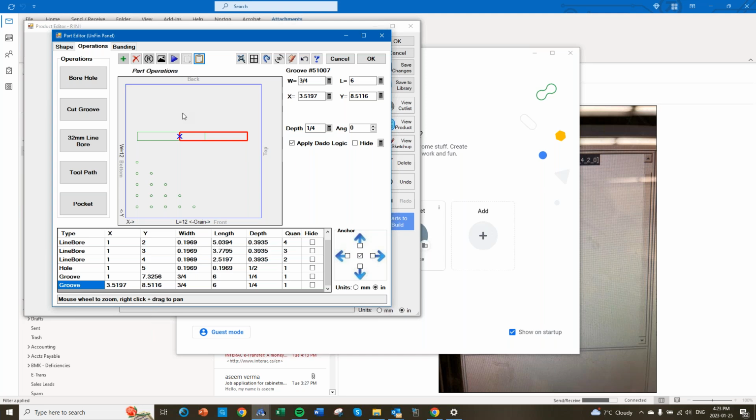All right, let's put that over here and we'll make that guy 1/4 inch wide. Actually, you don't have a 1/4 inch bit in there. Let me not do that. Make it 3/8. Yeah, you don't. Okay, so we'll go ahead and just make that 0.377, just a little bit wider than 3/8 of an inch.